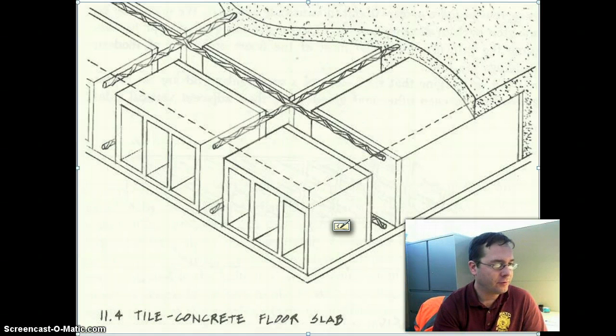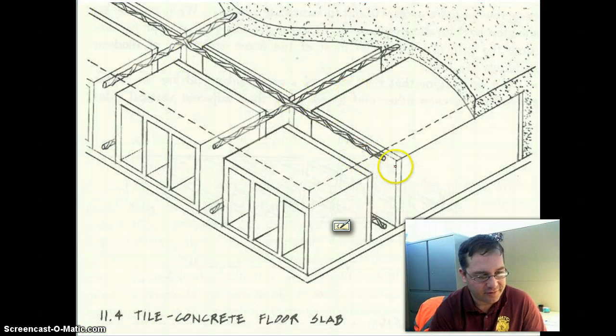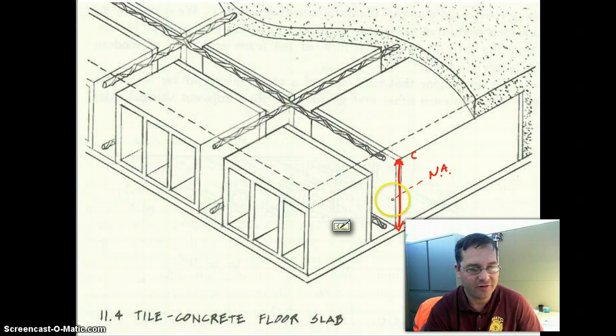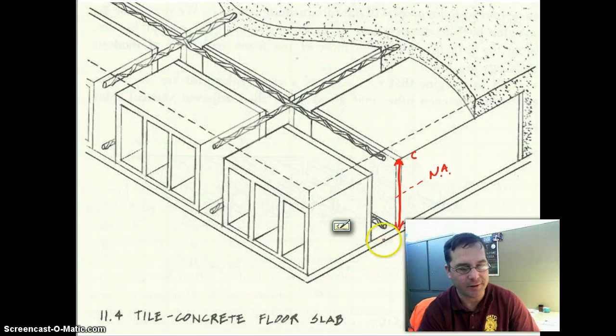Remember that, really what matters for the strength of this slab is this relative height, right? How far we can separate the material that's under compression from the material that's under tension. And for the moment, I'm going to say that the top's under compression, the bottom's under tension, and recall that halfway in between we have this neutral axis, which is neither under tension nor compression. So the real strength of this floor structure is near the top of the floor above and the ceiling of the floor below.